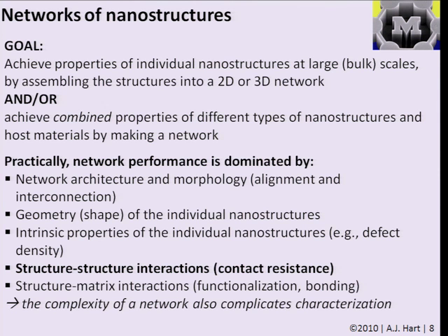Likewise, the strength of bonding between nanotubes and a polymer has a big effect on the final properties of that composite. And in the case of thermal properties, the matrix can also involve itself in phonon scattering as vibrations go down a tube. The fact that it's mechanically coupled to something around it can also dramatically affect its properties. All these geometric, topological and contact issues complicate characterization.